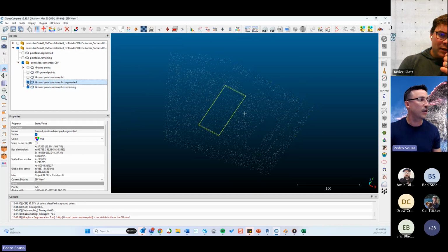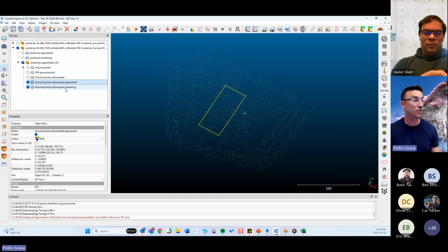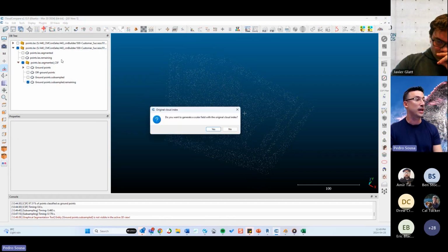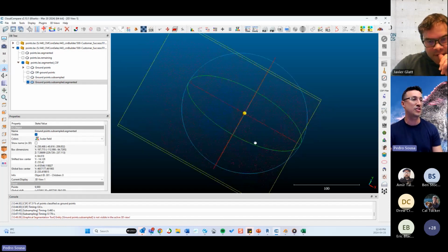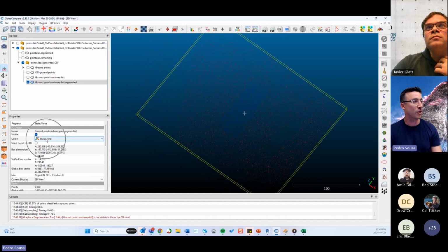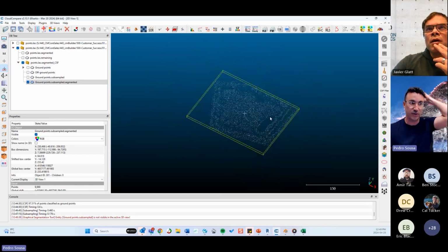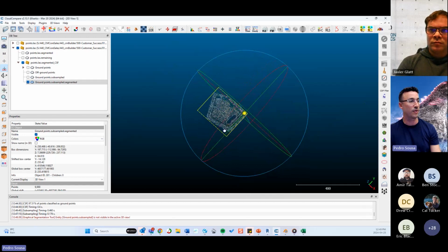After you do that, if you have 2 point clouds that have different resolutions, you can select those 2 point clouds and then click on this button over here, and you're gonna merge that point cloud. It will give you this change of color that's called scalar field, but you can go over here in colors and change to RGB. So it will show you the original colors of those points. So if you zoom out, you're gonna see something a little bit closer to what you had before.